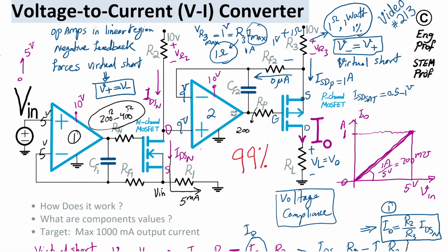These are not necessarily things that we can write equations for, but depending on what PMOS and NMOS you end up selecting, be careful that the PMOS has to be able to tolerate a continuous maximum current of 1 amp and a source-drain voltage up to 10 volt, which are very reasonable values. Nothing strange about them.